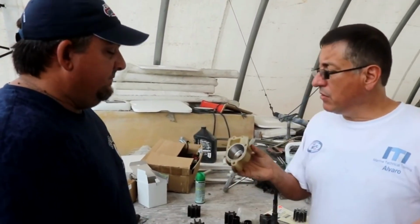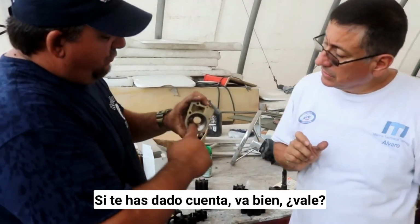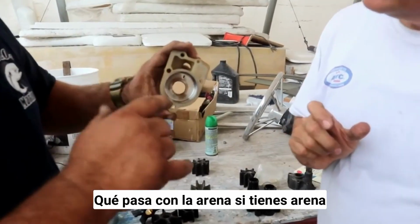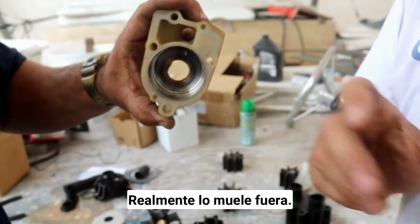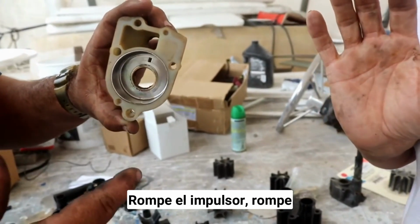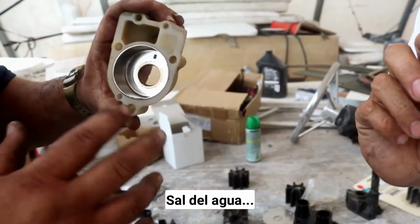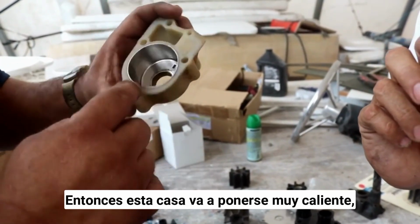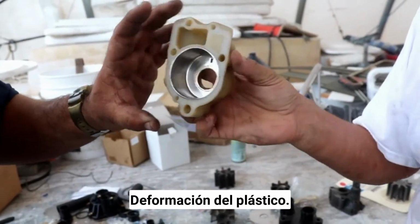What about the housing? The housing here, if you notice, is smooth. If you get sand, the sand becomes like sandpaper and cuts grooves in it and really grinds it out. It destroys the impeller, it destroys the housing, and if you run out of water, this housing will get so hot it'll actually melt the plastic all the way around, and the plastic is deformed.